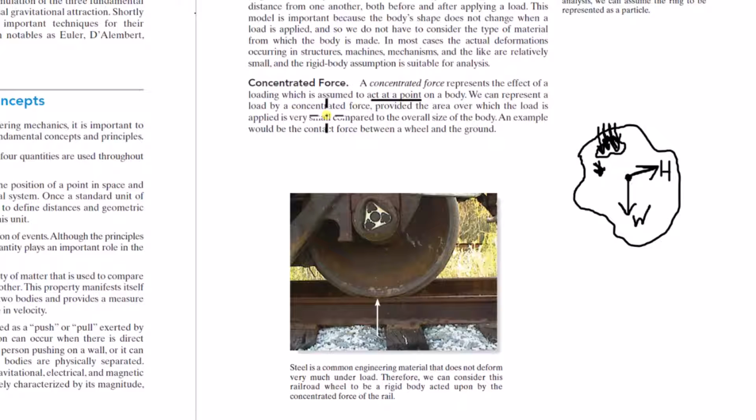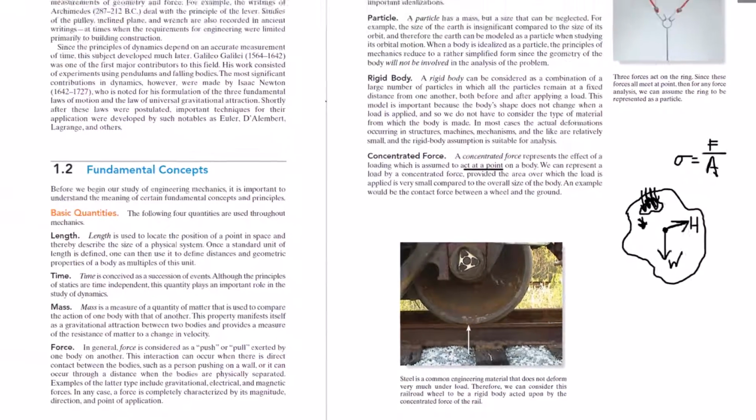Okay, this is strictly used for the type of problem that you're working. I want to stress that, because stress is force divided by area. Stress is how we measure the strength of a material, when a material is going to fail. Well, if the area is a point, then the stress is infinity. So if you're analyzing the strength or the deformation of a material, you can't model a force at a point. That makes no sense.